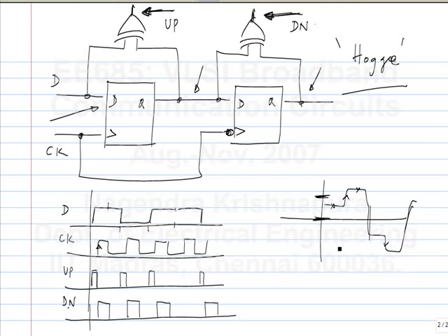So by combining all of those things, you can in fact come up with something similar to this. Essentially, you have the detector, and then it will be more complicated than for binary data. Similarly, if you want to clock it with some offset, that part also will be more complicated than for binary data. By combining all of that, you can get a phase detector that works on all of the transitions of PAM4 data.